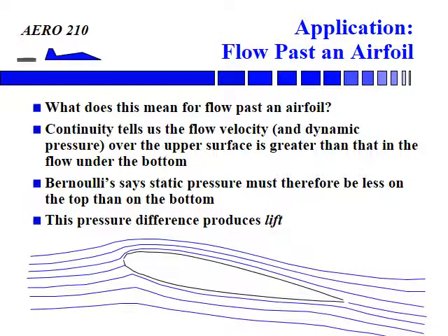So now let's apply this to flow past an airfoil. If you'll notice, the streamlines on the upper side of the airfoil are squeezed together by the shape and orientation of the airfoil. The streamlines on the bottom are not, so there is a velocity difference between the top and the bottom, and this produces a pressure difference between the top and the bottom, and this in turn produces lift.